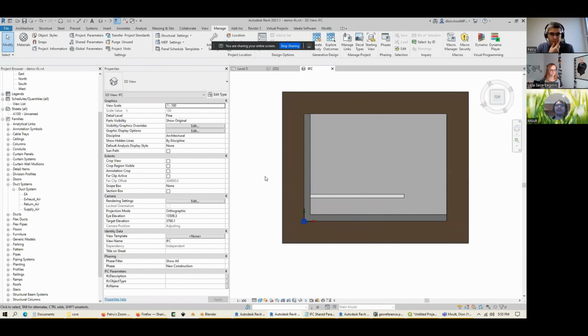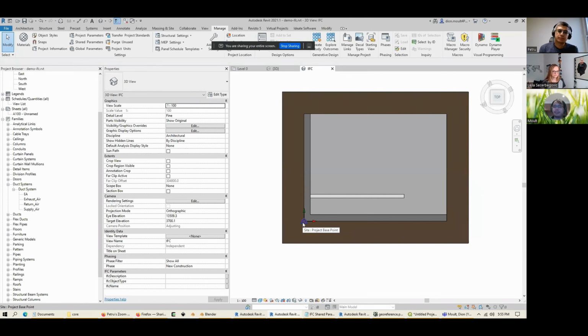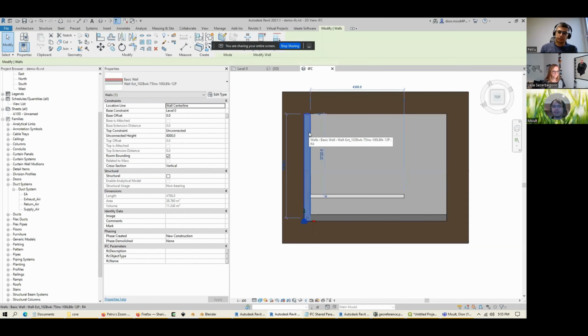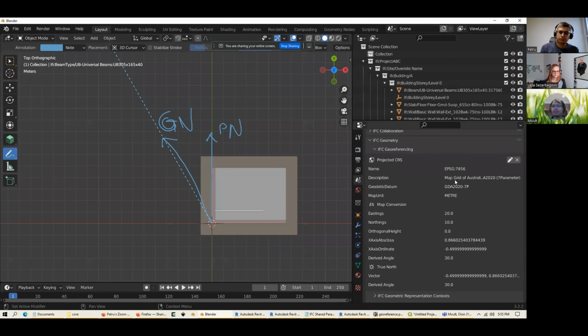And very often Revit users will link a survey into their Revit model. Some surveyors will show you multiple norths on their drawing, a true north and a grid north. It's important that you always set to grid north and not true north, because they're not the same. There's two different norths out there. Project north is just an arbitrary convention defined by the architect so that the design looks straight on the page, and that's fine. But when it comes to the real world, grid north is up the coordinate reference system, whereas true north, also known as geodetic north, points straight up to the North Pole.